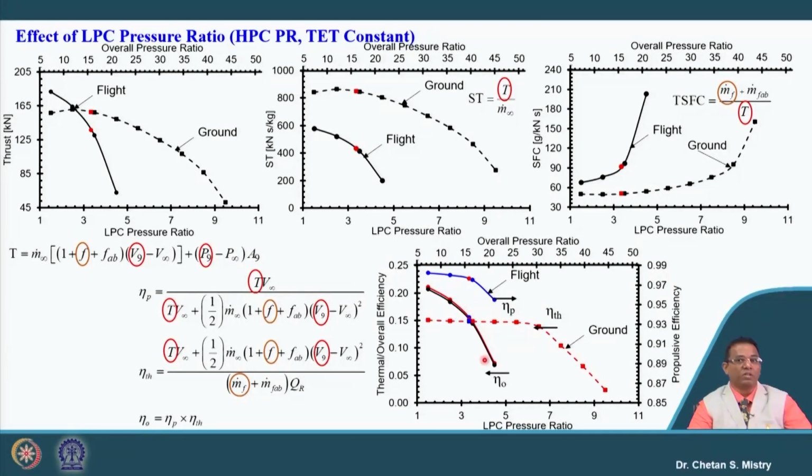So, as we have discussed, my operating pressure ratio is not beyond certain numbers. You can make your calculation, you can try increasing the LP compressor pressure ratio and just try to find what is the reason why we have not put these numbers here. You will realize the reason. What could be the reason why it is not happening? It is violating our second law of thermodynamics. Okay. So, just try to do that calculation and find the reason why we have not kept these numbers there.